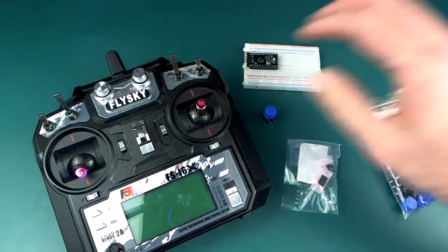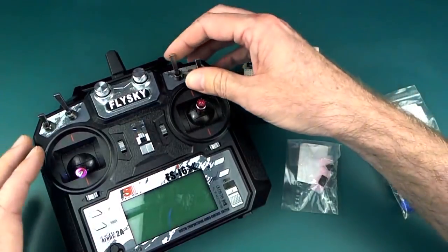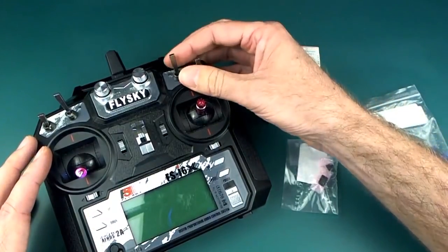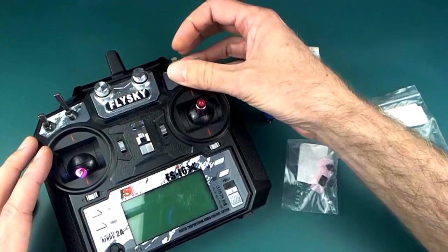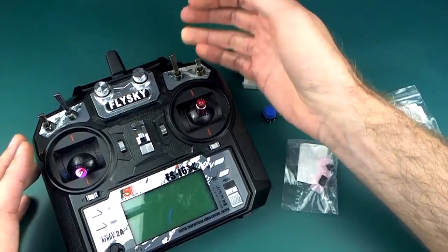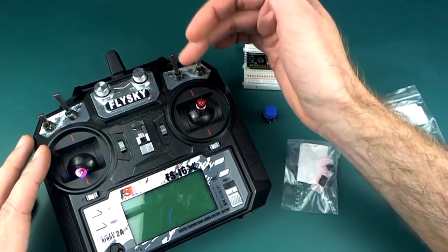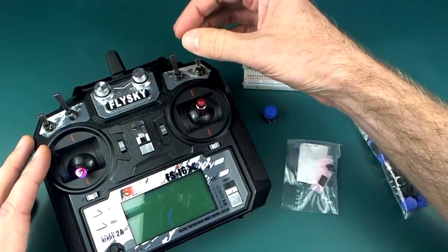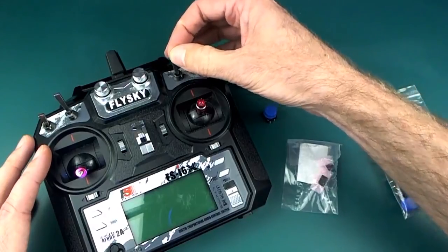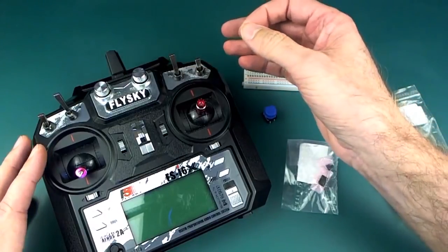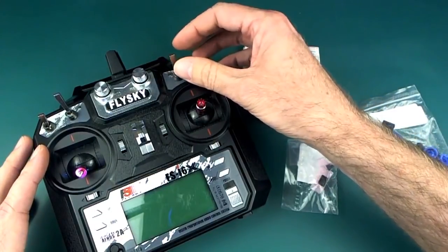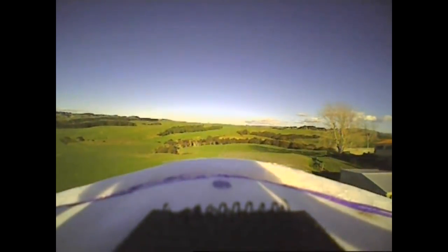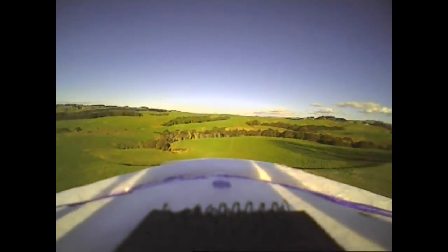The trouble with a lot of radios, and this one is no exception, is that often the highest number of positions of the switch that you have is 3, as is the case here. And what I typically do is I lose 2 of these positions because I want to have one that's always going to be manual, just in case I get into a situation, admittedly very rare, but I have had just once so far, a situation where the plane tip stalled. Yes, I'm looking at you, Skywalker Falcon.